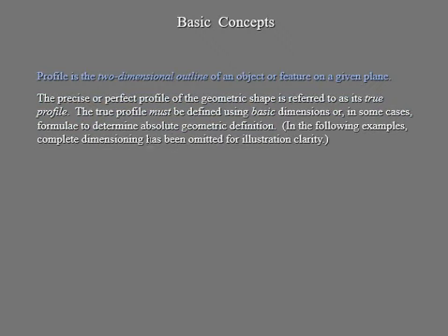Okay, I don't remember if I covered this or not, so let's take a look. Your precise or perfect profile cannot happen, because your basic dimension is going to refer to the two-dimensional outline of your profile, which is the two-dimensional outline of your object. So the true profile has to be defined by using your basic dimension.